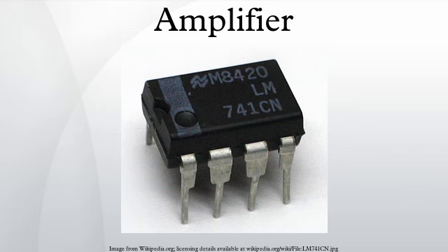Amplifiers are sometimes classified by the coupling method of the signal at the input, output, or between stages. Different types of these include resistive-capacitive coupled amplifier, using a network of resistors and capacitors. By design, these amplifiers cannot amplify DC signals as the capacitors block the DC component of the input signal. RC-coupled amplifiers were used very often in circuits with vacuum tubes or discrete transistors.